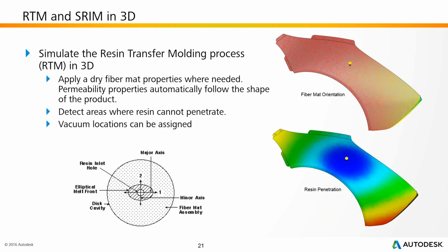the conclusions from the material orientation into the RTM solution, and properly account for this, because the permeability is now an element property, and you can give every element in this part a different permeability. So when you know what these are through another draping code, you can apply the right properties. I see there are some questions popping up, but I will take those later on in the presentation.